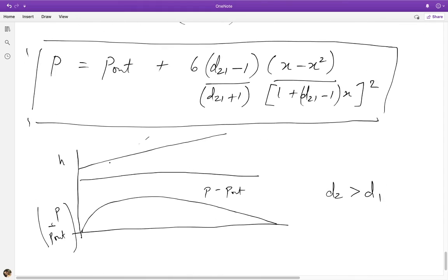What you would see is that there would be a Couette component but also a Poiseuille component because of these pressure variations. And that's something you can calculate easily. We just need to calculate dP dx and substitute into the analytical expression you have for u. And then if you calculate du dx, you get dv dy, and then one integration gives you v.